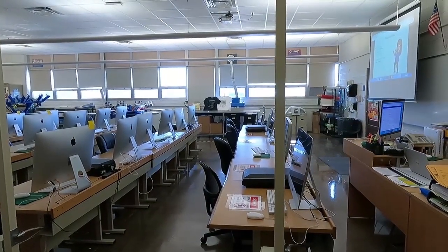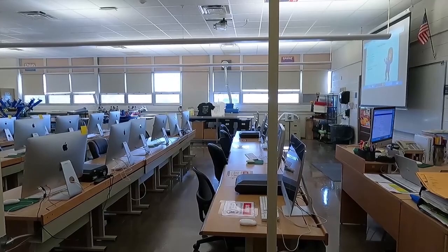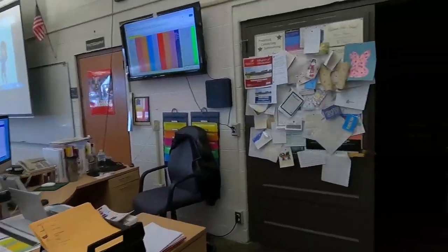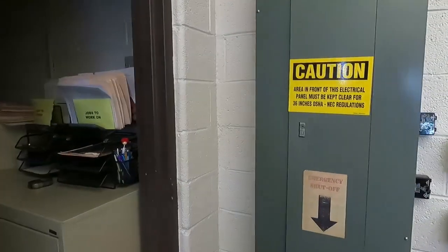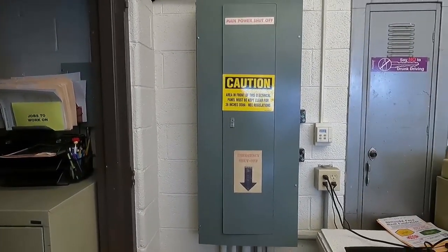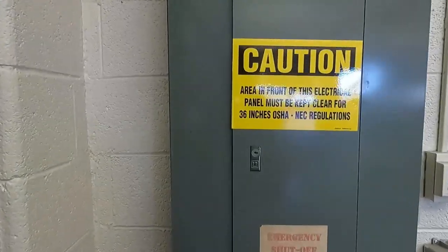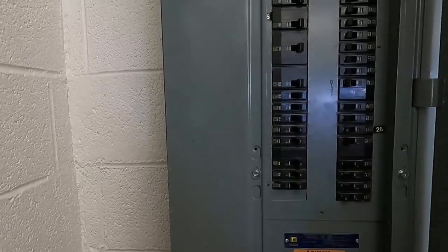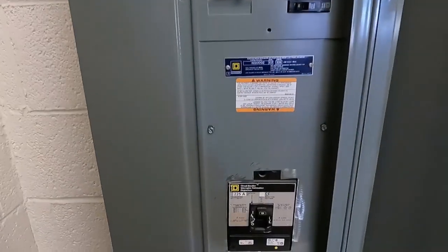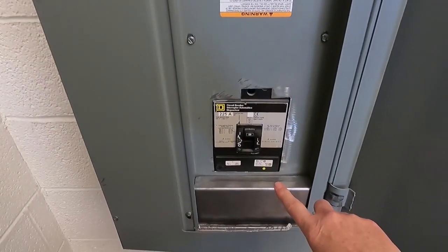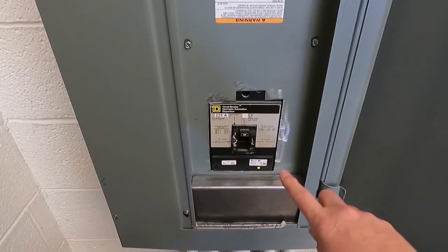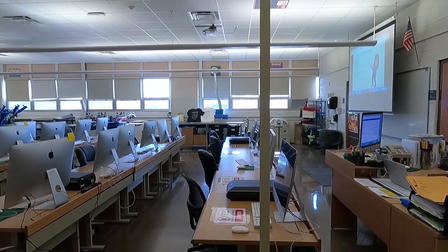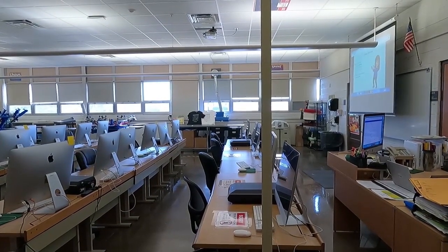And then you will go to the designated area. If for some reason there is a fire or some electrical charges or anything that requires you to turn off the electricity, you need to come to the electrical panel, open it up, and turn off the main disconnect switch. To open it, you press the D underneath the lock. It opens it up, and then the bottom switch, you can turn it off, and that turns off all electricity to the room.